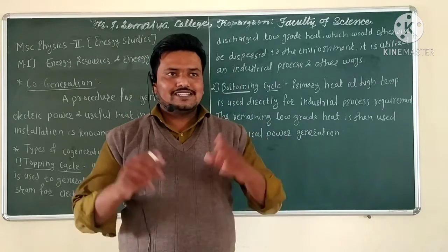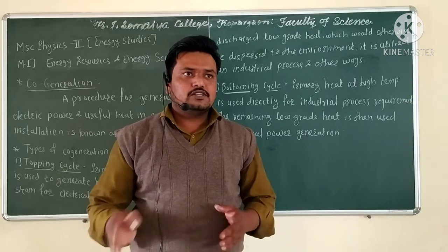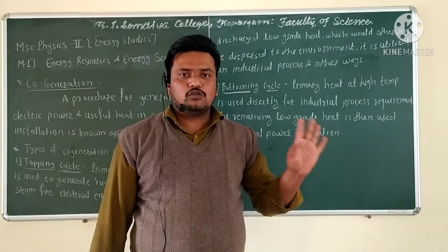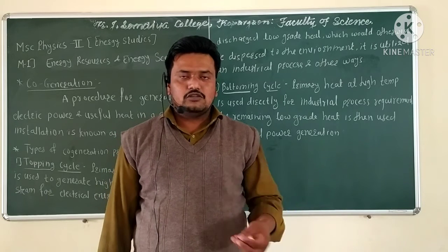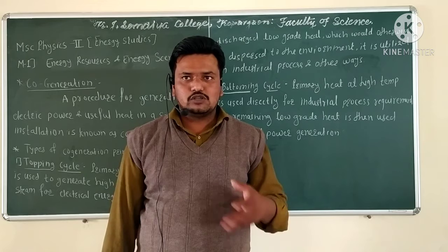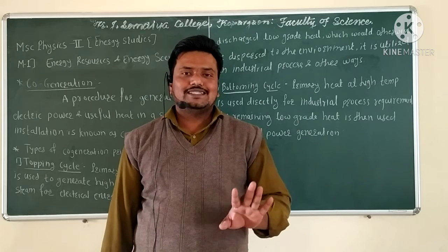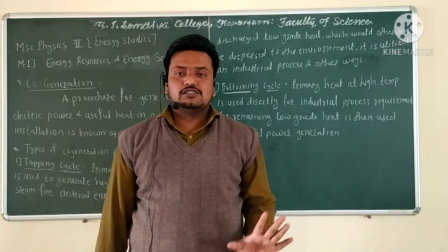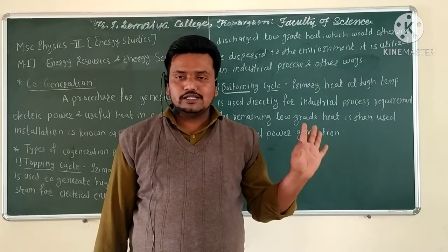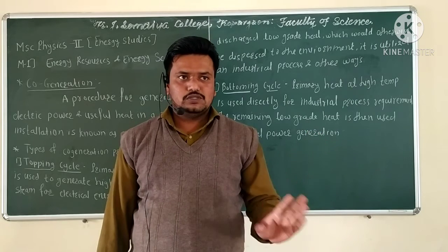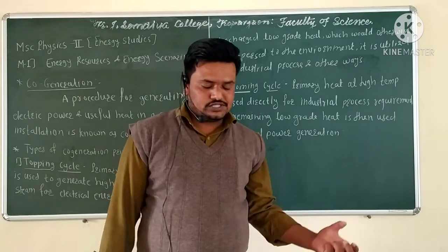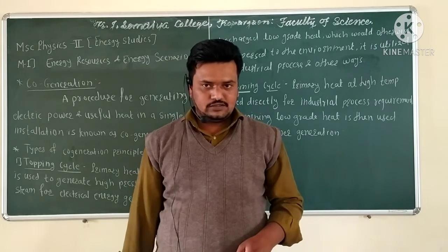So what is the difference between these two methods? In the topping cycle, the high temperature, high pressure heat is first used for electricity generation, and the low grade heat is used for other purposes like industrial applications.